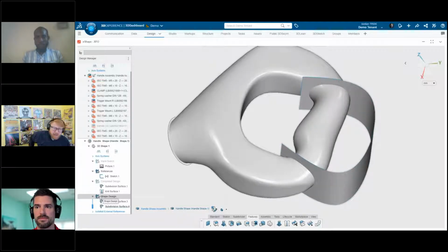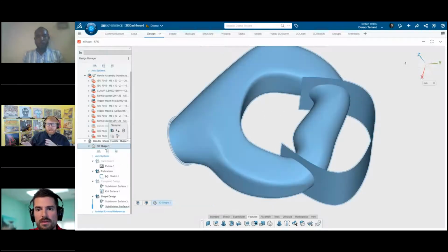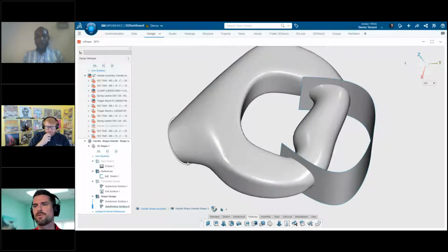Sure. And the cool thing, we have these things called ordered geometrical sets, which sometimes we use as just a way to separate out bodies. Like in SolidWorks, we have a surface bodies folder and a solid bodies folder. Does it really matter to separate that out, Andy? We just want the final surface to be in a unique ordered geometrical set, right?